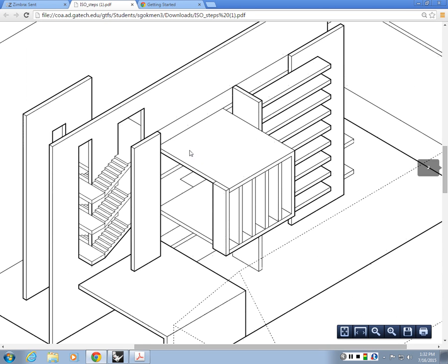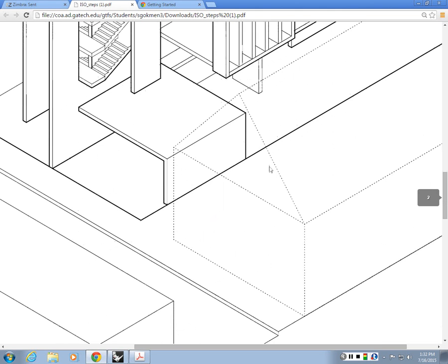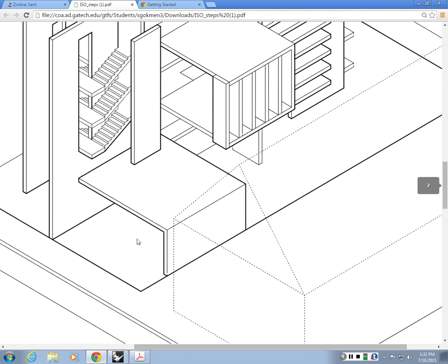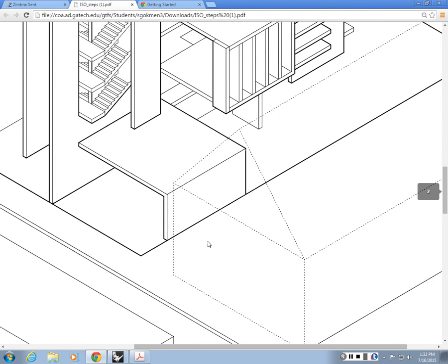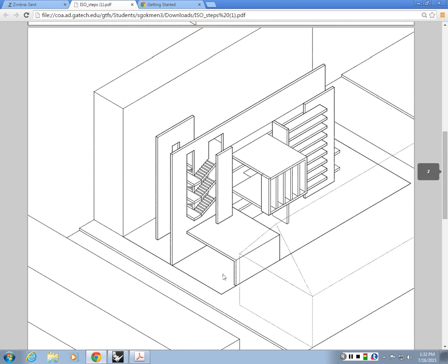And the next thing I did was to make the stairs or secondary details as light as possible. So these parallel lines could be thinner, these could be thinner. And one important thing I added was to make this building dotted, because we want to show information behind it. So it's kind of treating it like a ghost, right? We will be doing this line style to this building in this view, and when we do it in the opposite way, we're going to do it to this taller building as well, because we want to show information behind it, so we need to make sure that it's dotted.